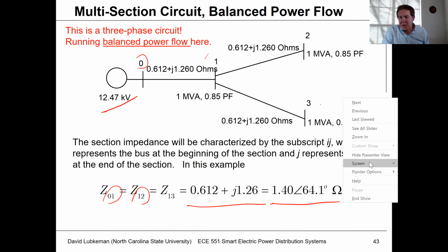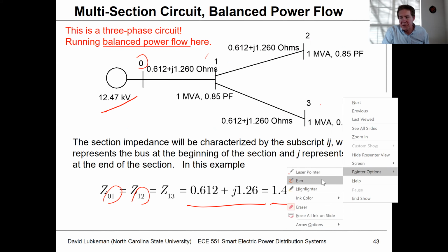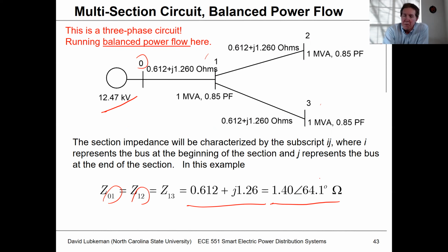As far as the sequence of all this, and the sequence is important, I start from the end nodes. If I had 46 amps here and I had 46 amps here, then on this line I would just sum up all the loads and I would get 46 on the line. I'd get 46 in the line up here, right?